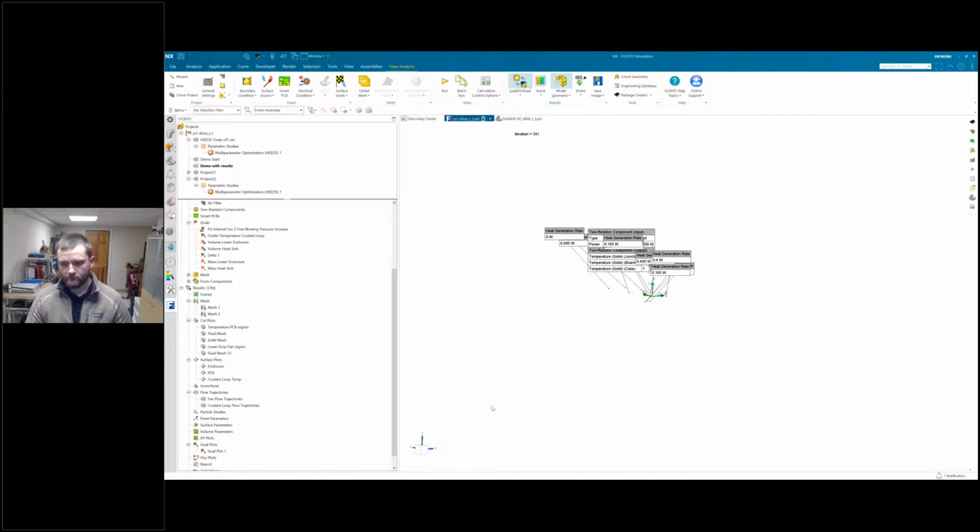Let me just go ahead and set our next step here. And we want to have this as a thermal design power of 1 watt. And our die length and die width we'll keep as the default 1.8. And our package thickness type we'll keep as thin. And we'll just go ahead and hit create.